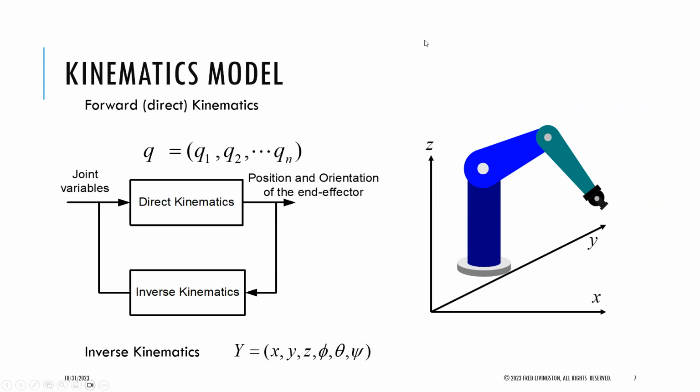And this is a better drawing of that system here. Where is your tool frame? That's important. Where the object you want to pick up is important. And you may want to know where the frames of the whole system are, and that's for collision avoidance. If I'm picking up here, I want to know what my end effector is, but I also want to know what these links are. So I'm not trying to pick up an object through this table here. I might have to go around and pick up the object here.